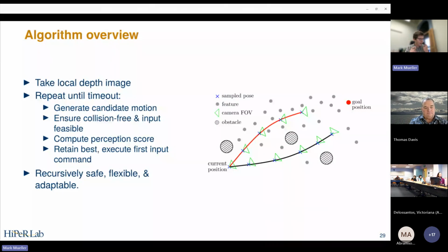One of the things we're interested in is, to what extent can I estimate the current wind and the gusts from, say, just the IMU data that I have? On the one hand, can I do better than an array of pitot tubes? But also, can I be more robust? Pitot tubes can get blocked by something, stuff can go wrong.